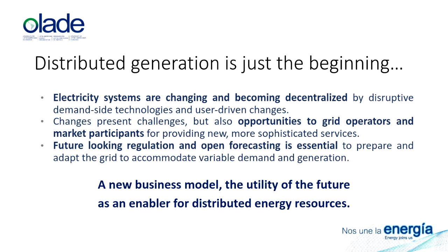But now that this demand is changing, it makes a lot more sense to think of more complex tariff structures, such as the ones that we have in commercial or industrial users. So we might see a shift to having capacity charges on smaller and smaller users, which should not impact the total cost of your electric bill, because if you're still paying for the same cost of the grid and an X amount of energy, when you add up the cost of capacity or the cost of distribution grid and the cost of the electricity, you should come to the same number.